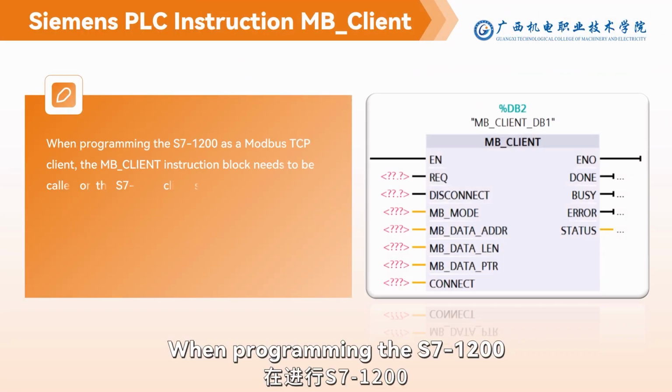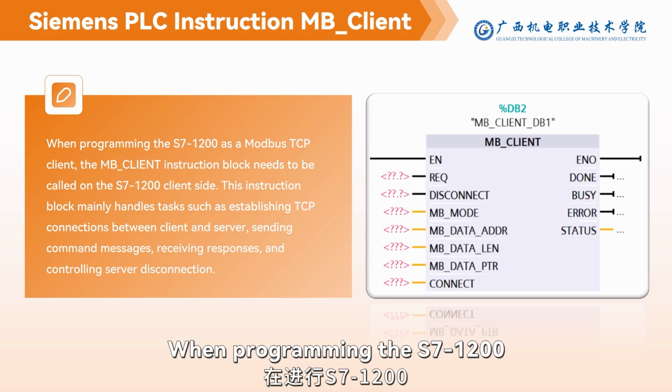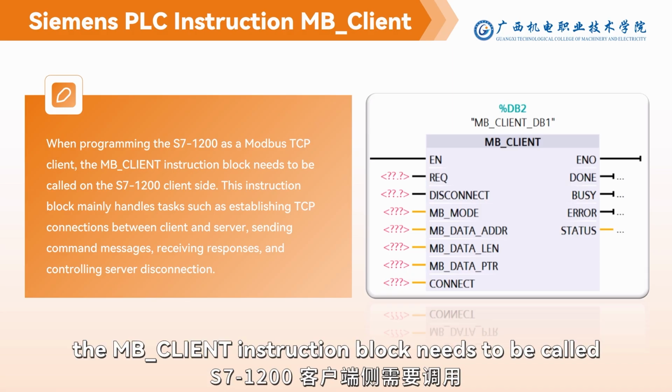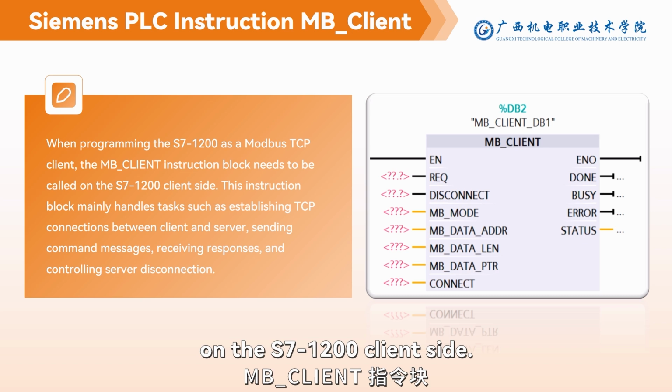When programming the S7-1200 at the Modbus TCP client, the MB client instruction block needs to be called on the S7-1200 client side.